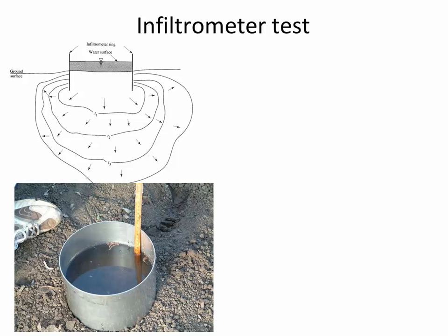All right. Here's another device, sort of like the tensiometer, a kind of an ingenious way of being able to experimentally determine the water's capacity for infiltration. And this is called a single ring infiltrometer. And I know this looks like it's a pan, but it's not a pan. At the bottom, it's open. So it's just only a ring. And at the bottom, it's open so that you can set it down into the soil gently. You don't want to jam it in and pack the soil and disturb it. So they gently will set this down into the soil and maybe embed it a centimeter or two.